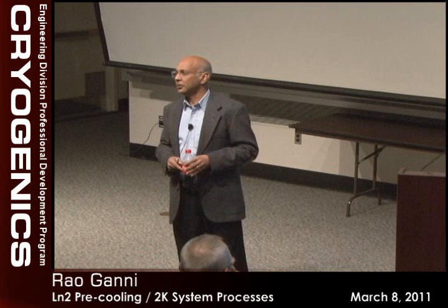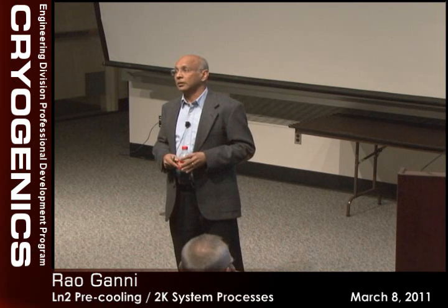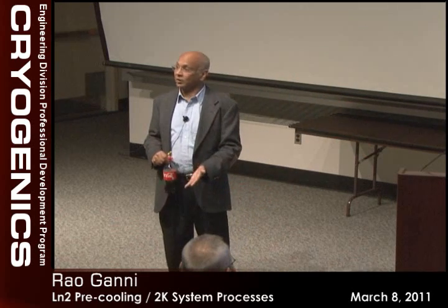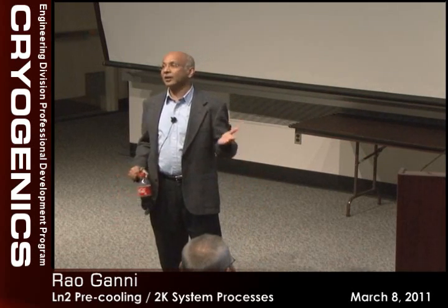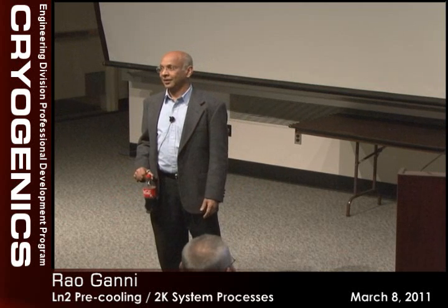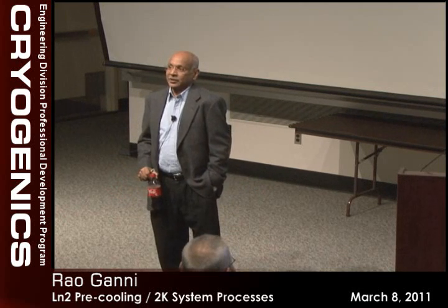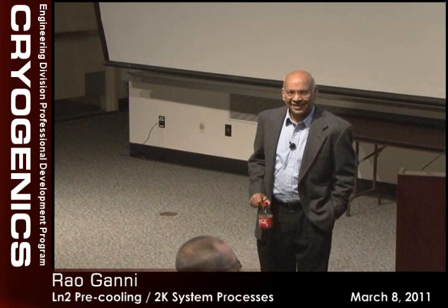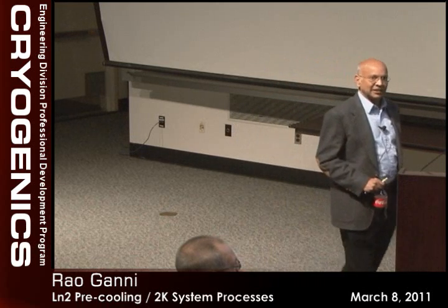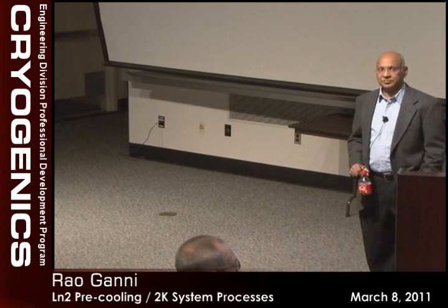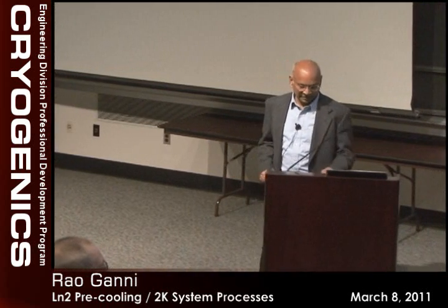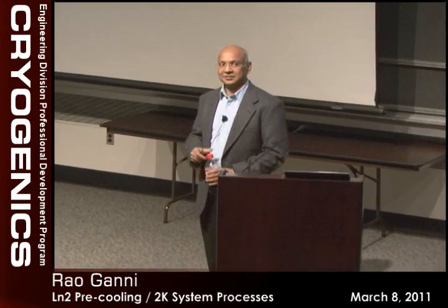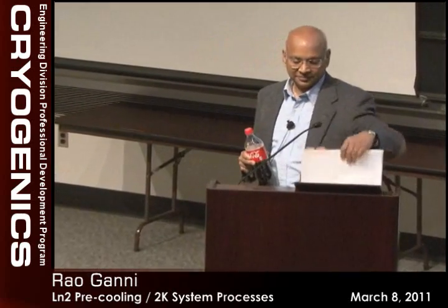Okay. You mentioned you're using oil, there may be water in there. Oh no, like we said, the cold box will clean it up. Whatever is coming back from the cold box is completely clean. Anything left is frozen in the box. At 4 Kelvin or 2 Kelvin, we have nothing except helium left. We take out the moisture and the light ends prior to putting the oil into the compressor. So what you're pointing out is that if you did have moisture in the oil, it would end up in the cold box. Yeah, but in reality, we process the oil to remove those contaminants before we put it in.